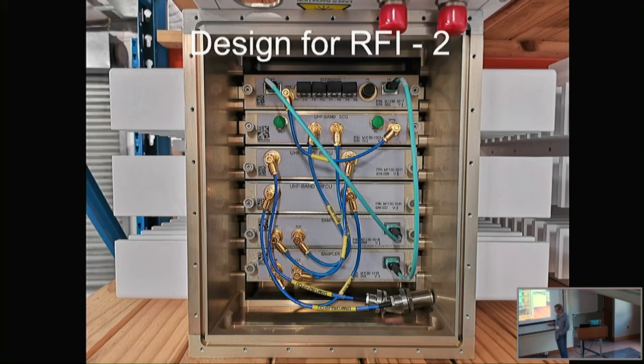Then those modules, so that module is not here, but it would slot into one of these slots. These are now each individually shielded. So on top of the PCB design and the internal shielding, they're individually shielded, and they're interconnected with fiber. So it's short range, but the fiber prevents any coupling from one unit to another. So here we have RF conditioning units, and we have samplers. We don't want those things to couple to each other.